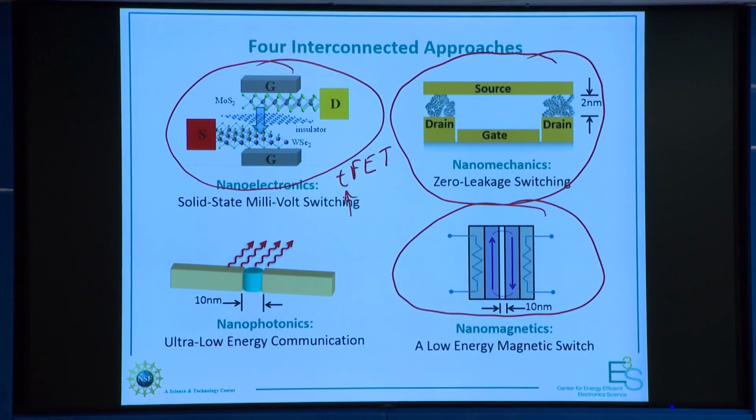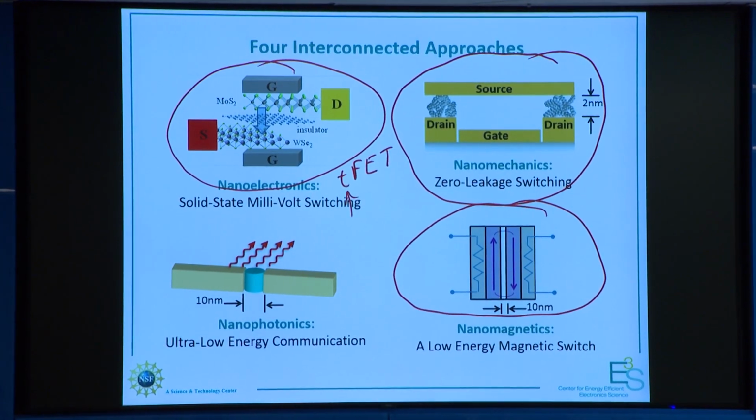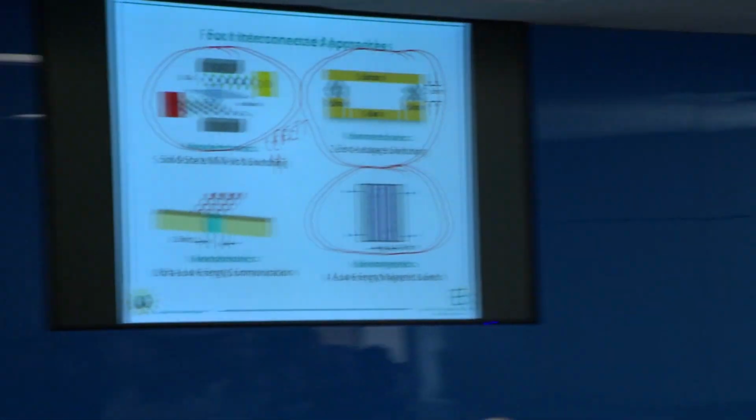Now this looked like a long shot, but just in the past few years, there have been new discoveries in magnetism where you can switch a magnet with ever less current. So there's now something called spin orbit torque, where you have a microamp, and you can switch a magnet. You just switch a magnet. You can turn that into a resistor through a magnetoresistor, and I'll show you an example of that.